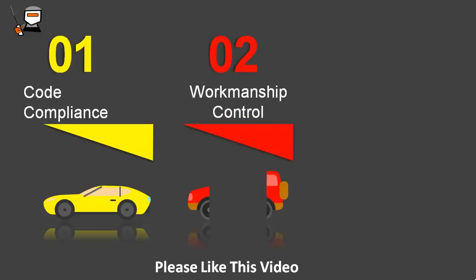Good workmanship is the standard that a competent worker should be able to achieve without difficulty when using the correct tool in a particular working environment. In practice, the application of the fabricated item will be the main factor that influences what is judged to be good workmanship, or the relevant client specification will determine what the acceptable level of workmanship is. Reference samples are sometimes needed to give guidance about the accepted standard for details such as weld surface finish and toe blend, and weld root profile finish required for welds that need to be dressed by grinding or finishing.